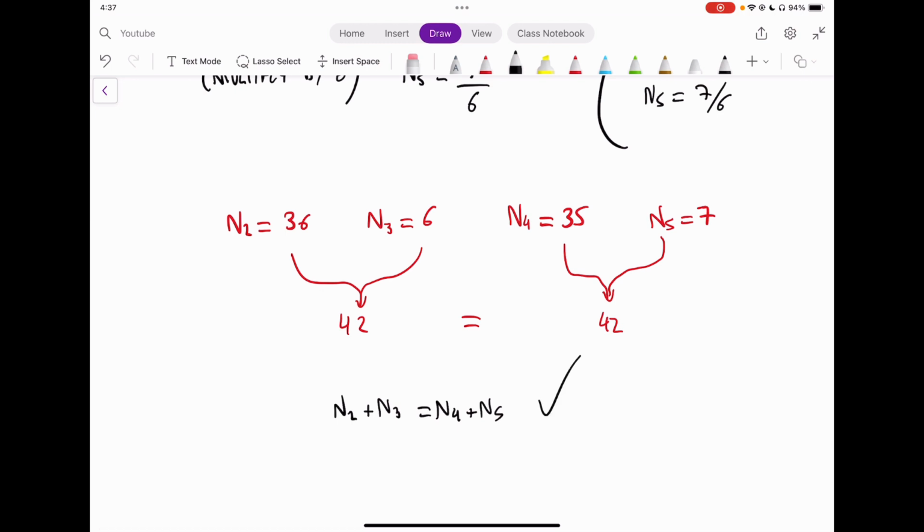The problem is that it still doesn't satisfy our interference. So we know that for our interference, we need at least 16 teeth. So now the next thing we have to do is, keeping these numbers fixed, multiply all the numbers once again by a certain value.